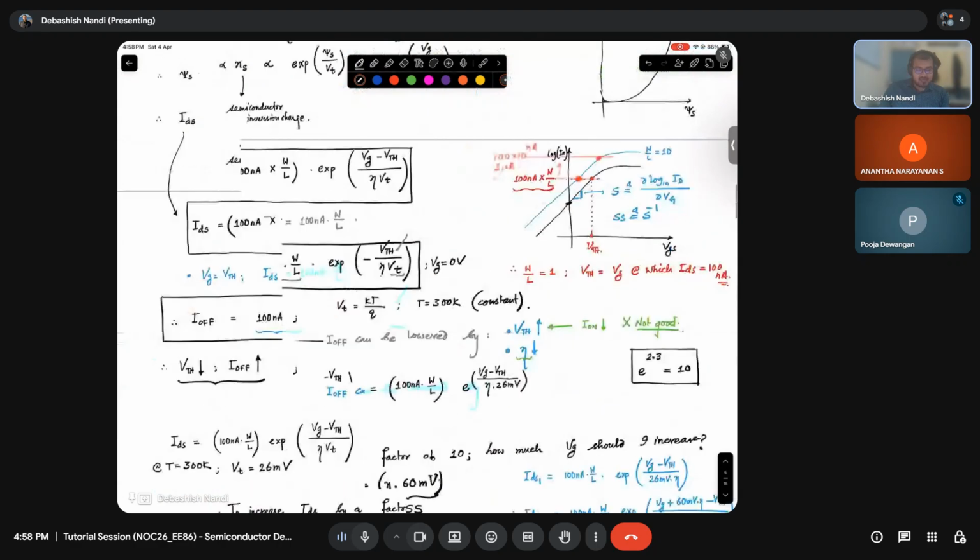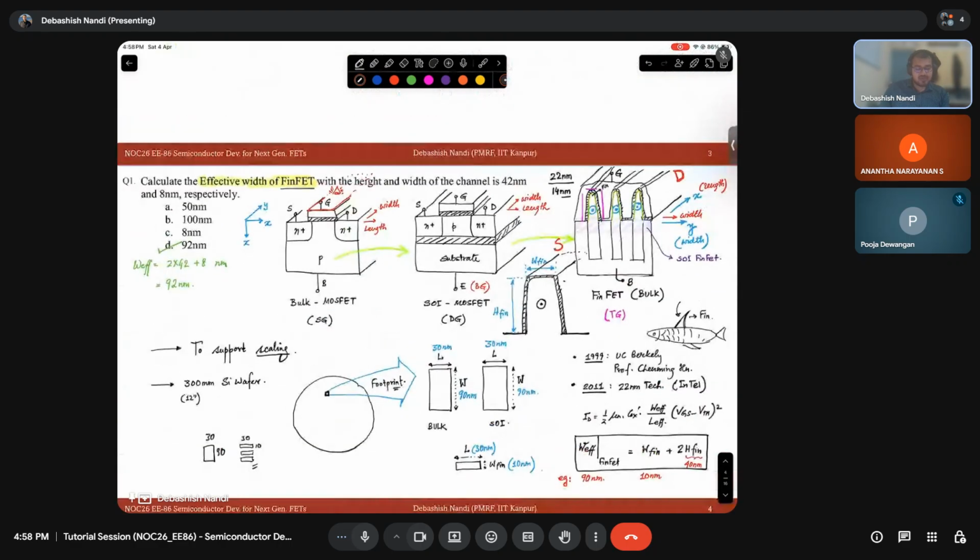Okay. So let's conclude today. We had an elaborate discussion about how we evolved from single gate to double gate to tri-gate or FinFET technology, and then followed by nanosheet. And we'll see some nuances with the nanosheet technology and its subsequent generations. We call them fork sheet and whatnot, CFET, complementary FET.